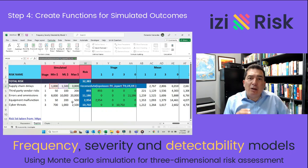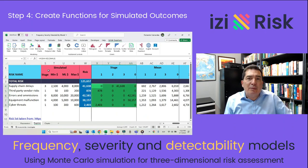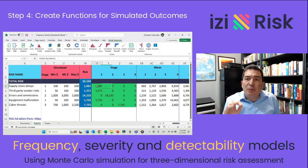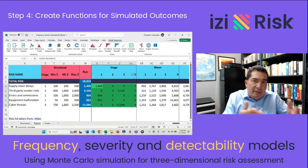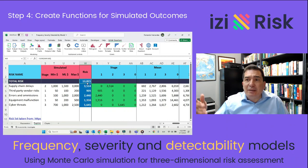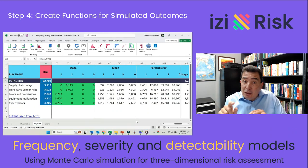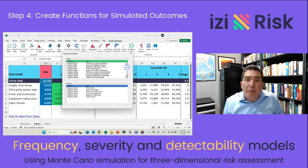We now declare input functions for the range X4 through AA8. These are the simulated outcomes per risk type for each one of the stages. 20 different input variables corresponding to 5 risks, each one of them evaluated at 4 different stages. We also define output variables: total risk on cell W3 and each one of the 5 different added risks for all stages on the range W4 through W8. Once defined, the Show Inputs Outputs icon allows you to list respectively the previous declarations of them.